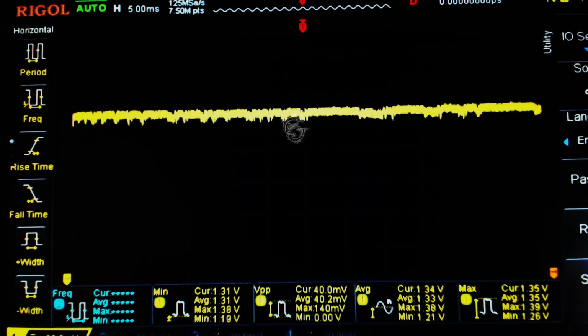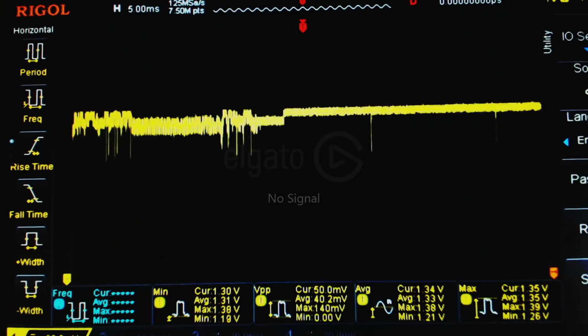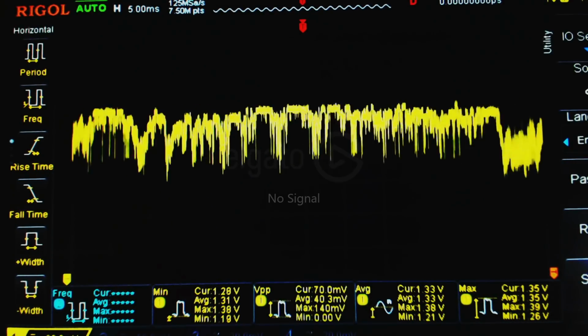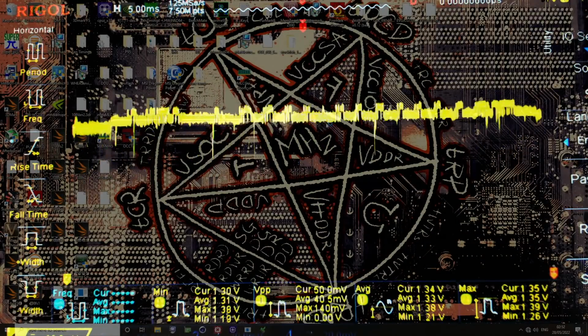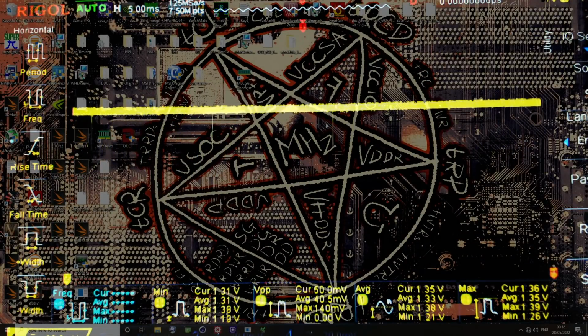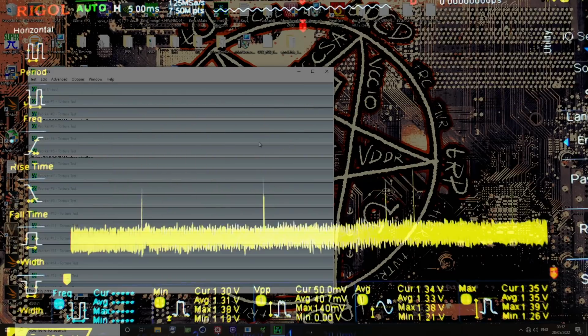This is the whole reason why on Asus boards it's actually super easy to identify, or well, I think on newer ones it might be a bit more difficult, but the first Asus boards that introduced die sense monitoring have a really obvious op-amp in the VRM area of the motherboard, because you can't just connect the Super I/O to die sense. I don't know that's for sure what's going on here, but the die sense shouldn't be affected by a BIOS setting like that.